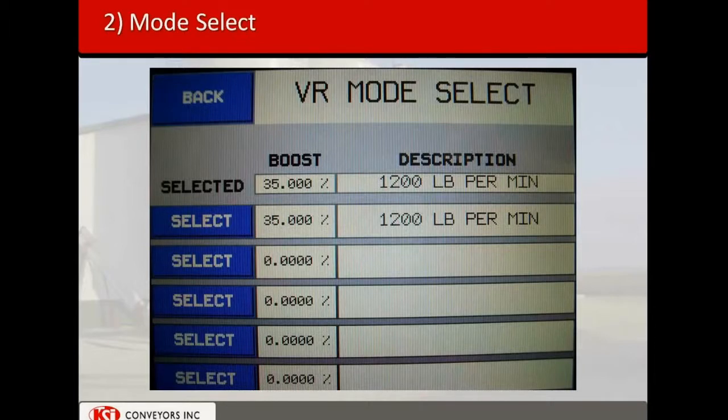The goal is to get your boost so that it opens as far as possible, as close to the target as possible, without overshooting the target. So if the gate spends a lot of time being about 40% open, we would want the boost to be maybe 35%, 5% under the actual of what it does during the run. And then a little description here allows you to say what this boost is for. Generally speaking,